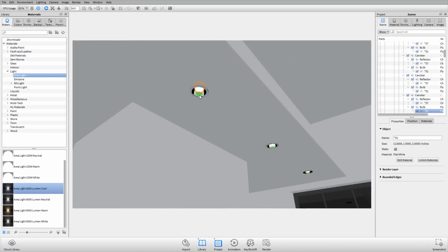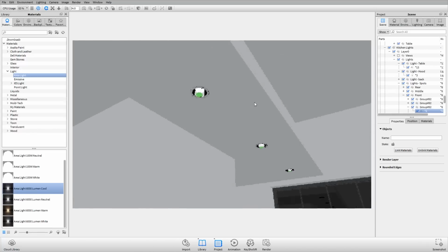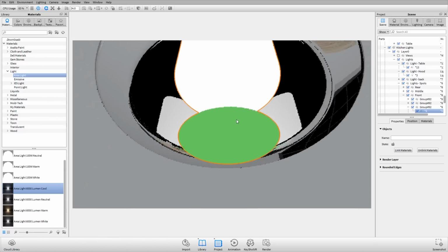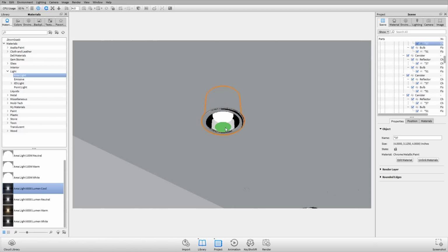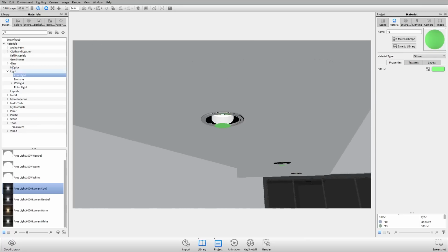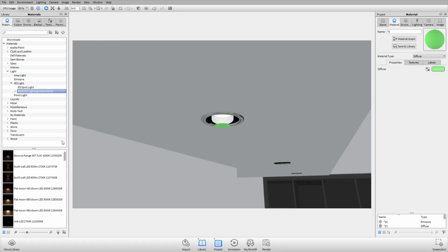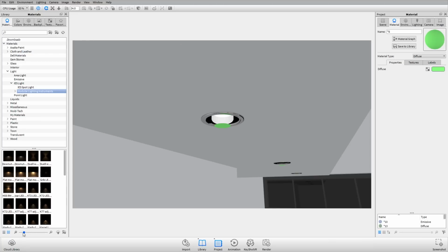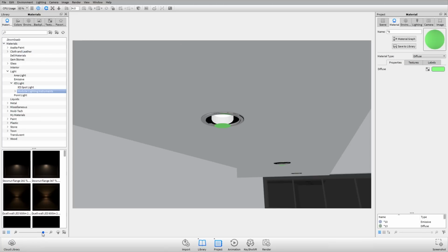So what we'll do here is that material should automatically be linked. So let me deselect it. What I can do is go to my lights folder, go to the IES lights, and take a look at my modular lighting instruments. Again, if you don't see these IES profiles, make sure that you have the full install of 6.2 on your machine, not just the update.